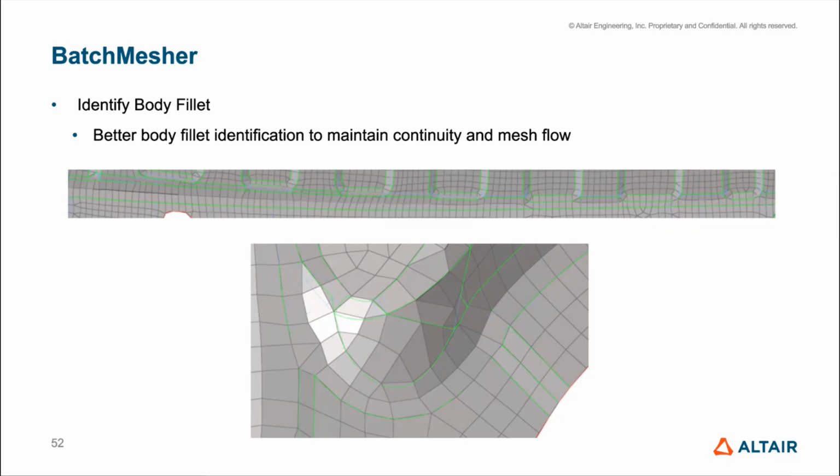So these are bigger regions and huge regions. If we identify those, and also adhere to our parameters given for the fillet recognition and meshing, then automatically the whole part starts looking better. So if there is a fillet line running across the part, and if we map that properly, then it also looks good from the mesh flow standpoint.